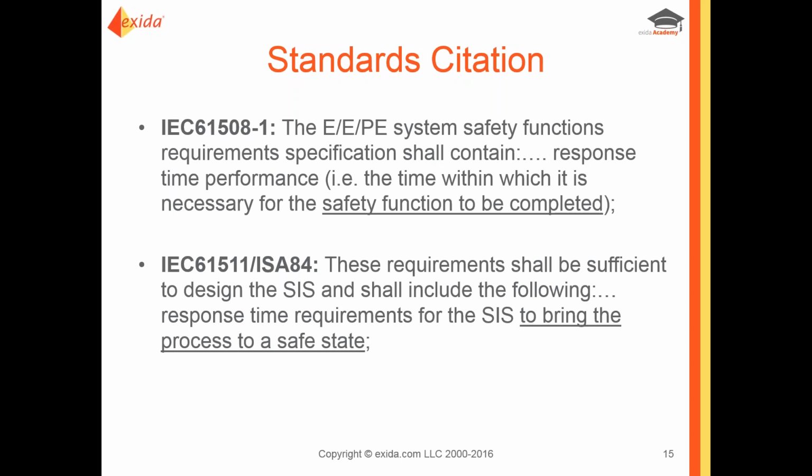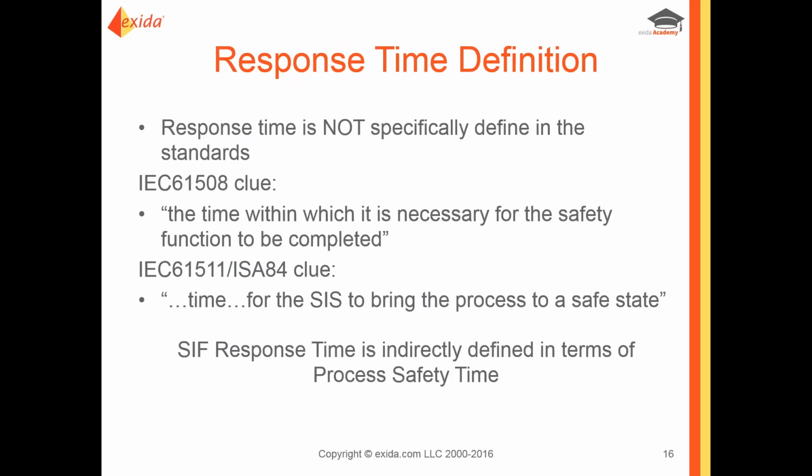So we've introduced the concept of needing to achieve a safe state as part of that function. As we're defining it, we look at these two to get the clues and realize that the SIF response time is indirectly defined in terms of our process safety time, because it's necessary for the function to be complete and to render a safe state.